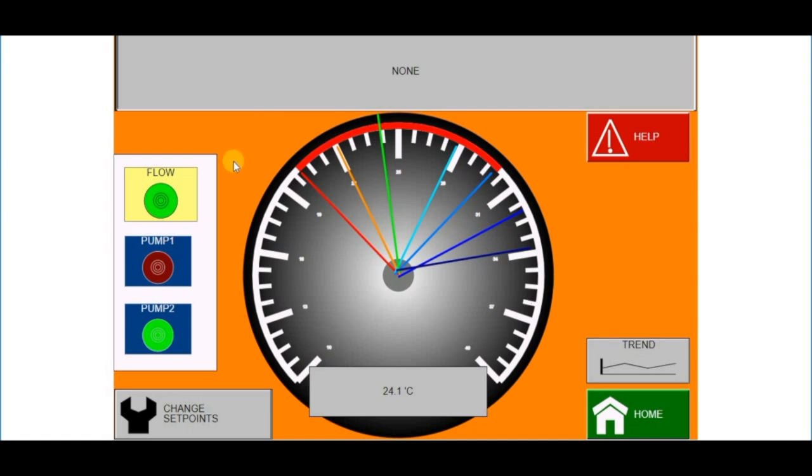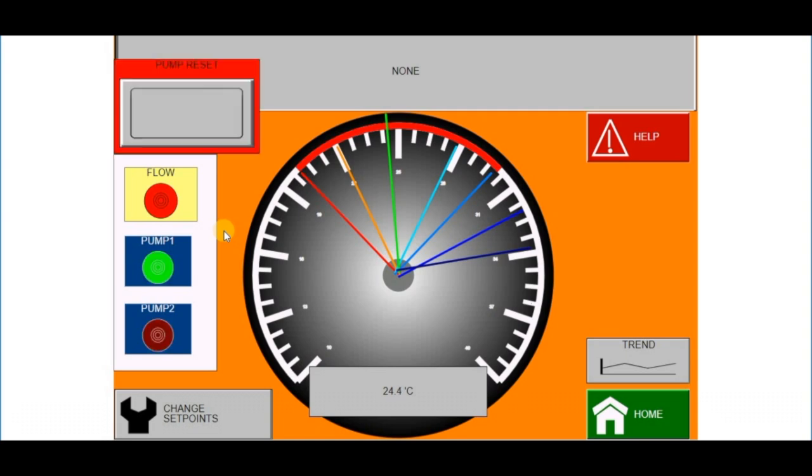Next thing we're going to talk about is a safeguard that we have for the pumps. We have a flow proving switch to tell us that the pumps are doing what they're supposed to do. But in the case where we're commanding one of the pumps to come on, but we don't have an indication of flow, we will automatically energize the lagging pump to instead come on and see if that can get the flow switch to close. So I'm going to demonstrate that now by killing the flow, waiting the preset amount of buffer time before the safeguard initiates. There it is.